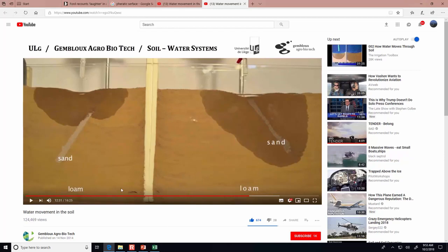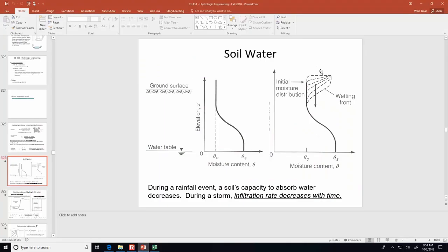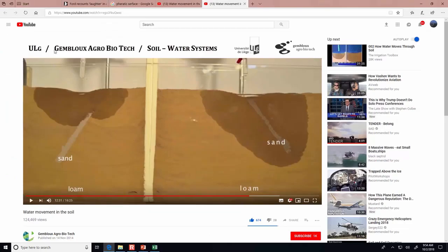But that's an important point, and I also wanted to tie it together with these figures that we're going to look at. And these figures seem abstract when you just see them for the first time and you're not able to relate it to this visual representation of the water penetrating down through the soil. So what we're seeing is the wetting front go downward and outward because of gravity and because of the suction/tension within the soil. So those are the two things that are bringing the water down. But then the difference between full saturation and just an increase in moisture.